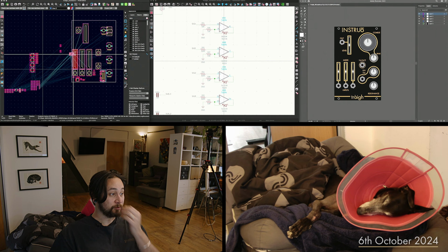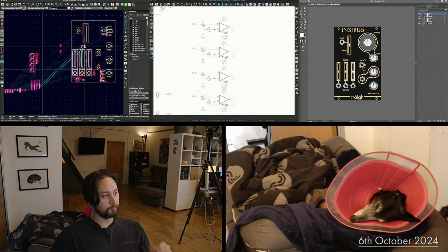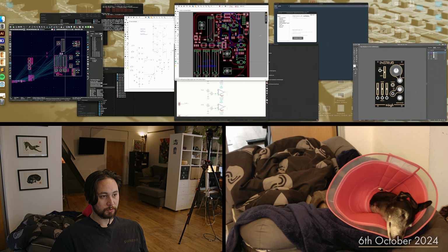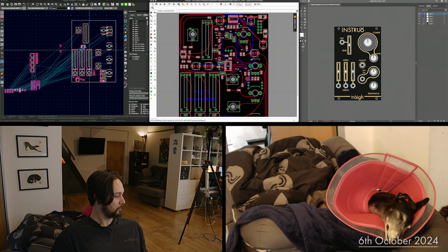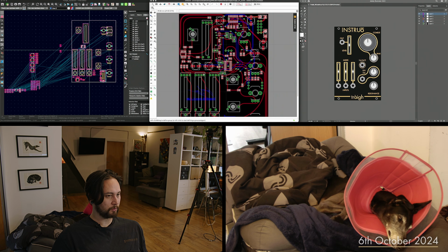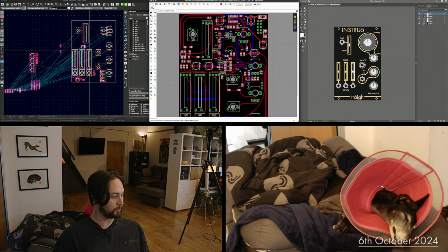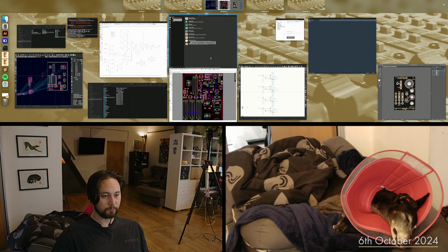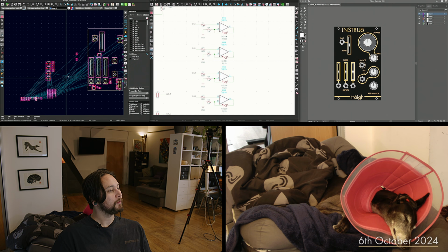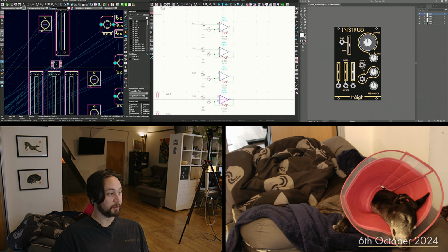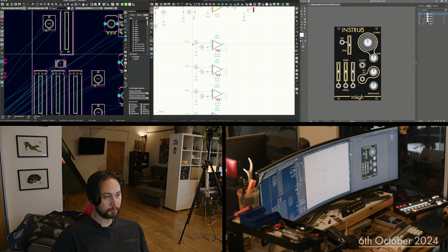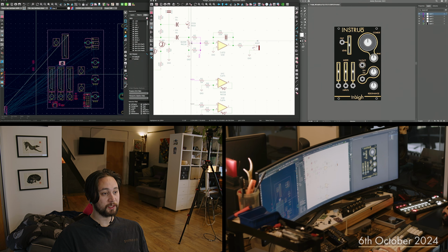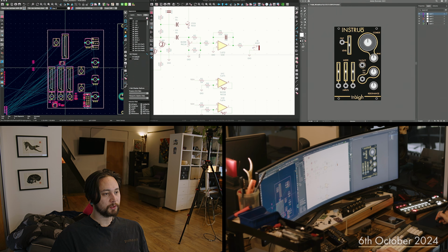So this is my LED driver. This is new from the original, because these LEDs were just fixed on, I think, a 10k resistor or something, hugely under limiting, so they were painfully bright in a previous batch. So I would change the resistors by hand a lot of the time, so they didn't completely ruin your eyes. This one, they're going to be dynamically driven by amplitude. So, actually, let me just double check. Signal 4, yes, that is post attenuator. That's what I want.